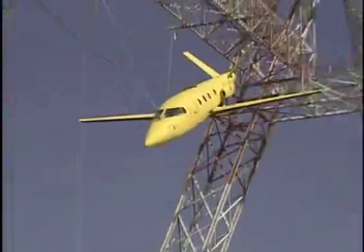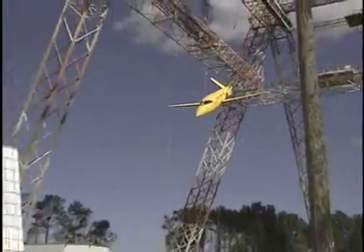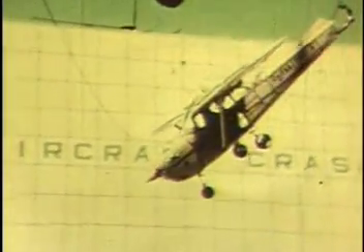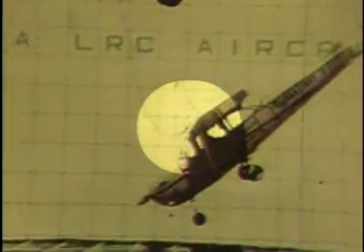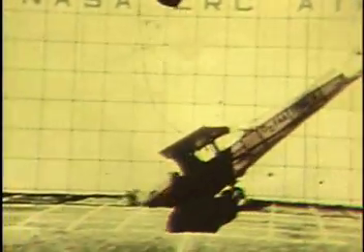The Impact Dynamics Research Facility is used to conduct full-scale crash tests of aircraft. The aircraft to be tested is suspended from the gantry, pulled back to a calculated release height, and then released to swing like a pendulum into the impact surface below. Just before crashing, the swing cables are released and the aircraft goes into free flight. The cables attached to the aircraft are released by pyrotechnics or explosions. It's pretty cool to watch.